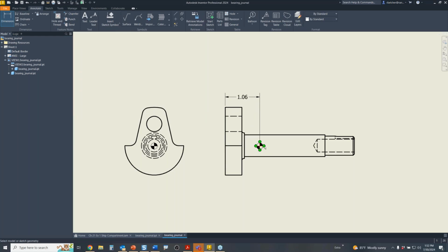And these little markers, that little crosshair, you can stretch these out. They're actually center marks. So if I drag these out, they're not center lines, they're center marks. So you might not want to do it this way, but you can drag these up and down if you need to.